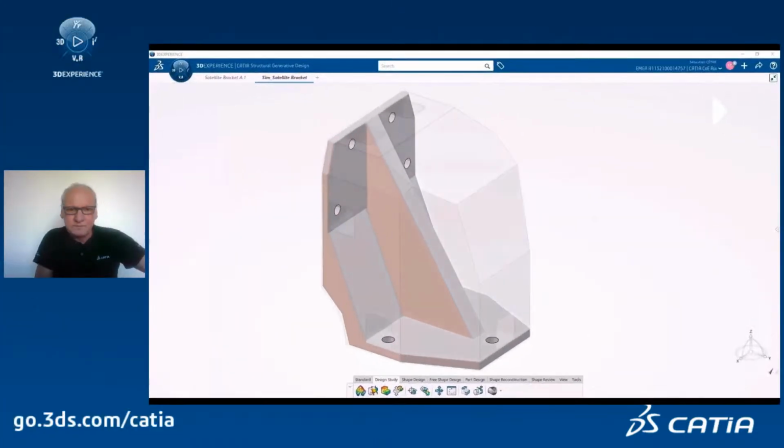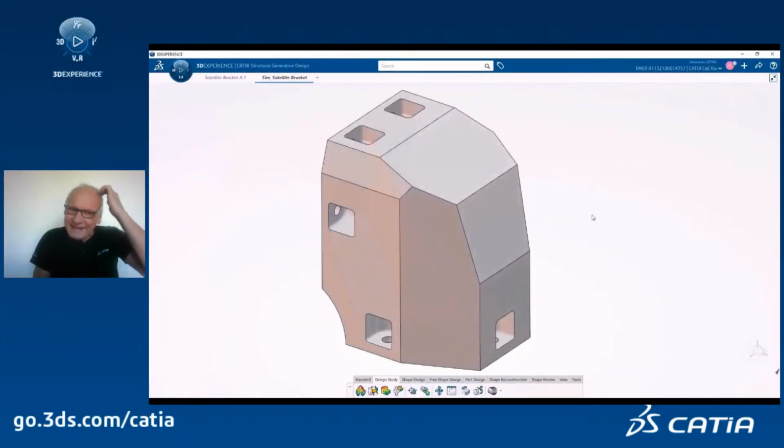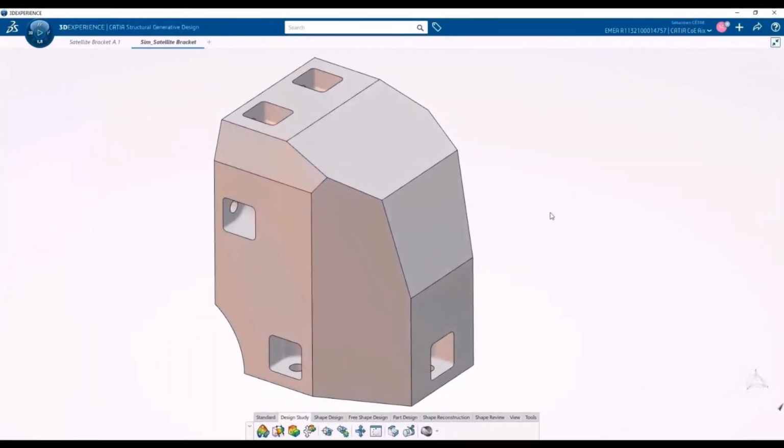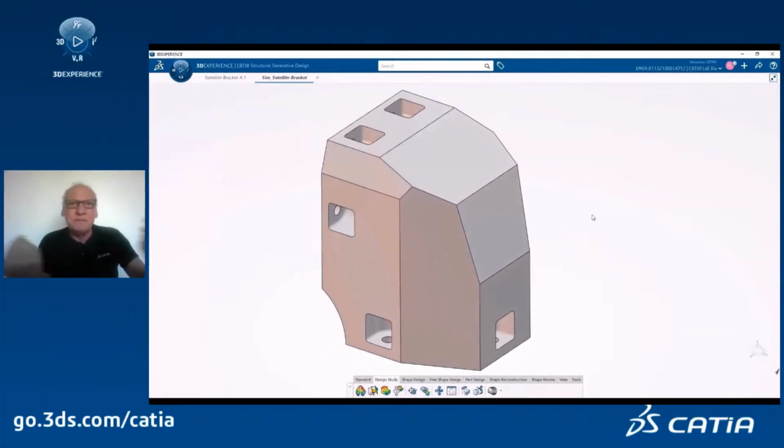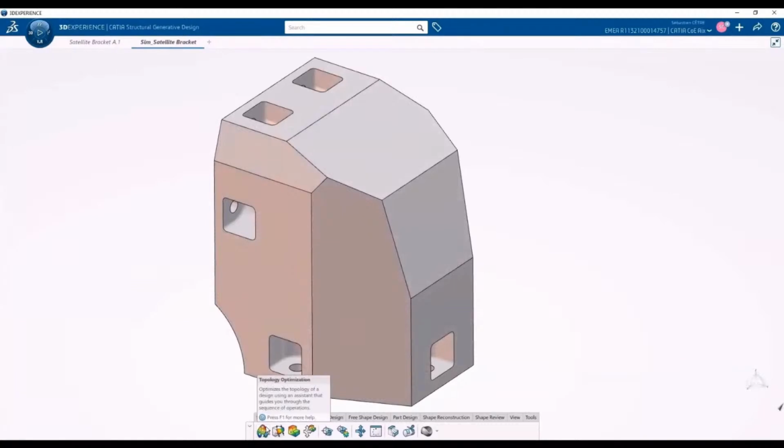Let's start. To begin with, I will deactivate some features to give more space for CATIA to find the optimal lightweighting path. Typically this is mainly the so-called design space, the allocated volume in space where I will design my part. A part is never alone; it's surrounded by multiple parts within an assembly, and this is a space where I can create my new design. So this is my design space, and I will enter